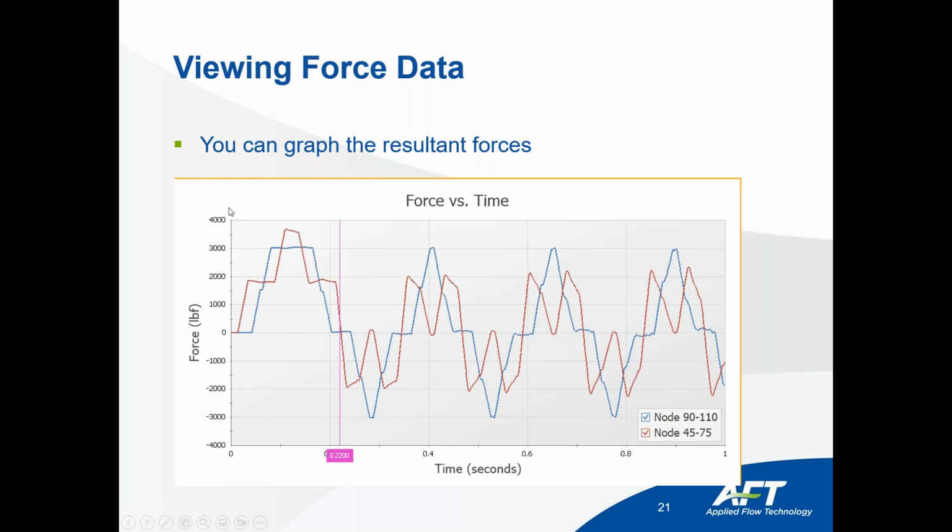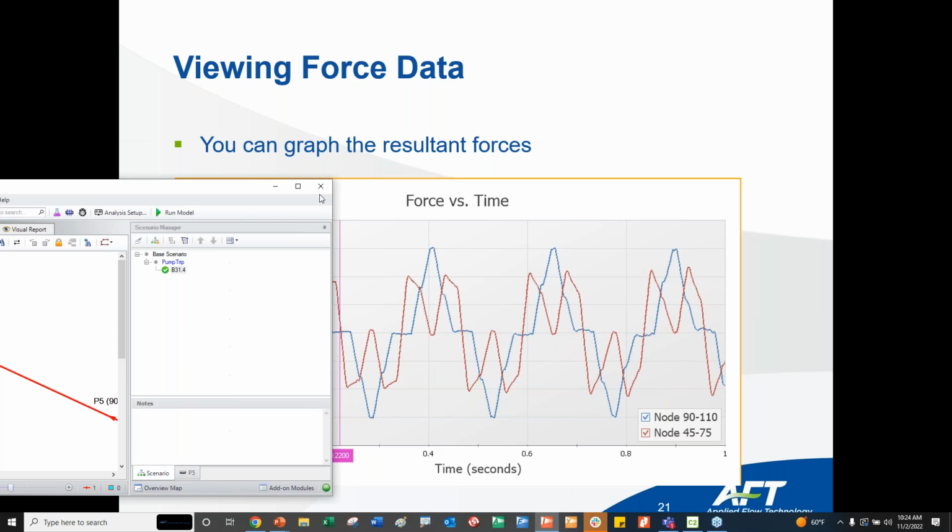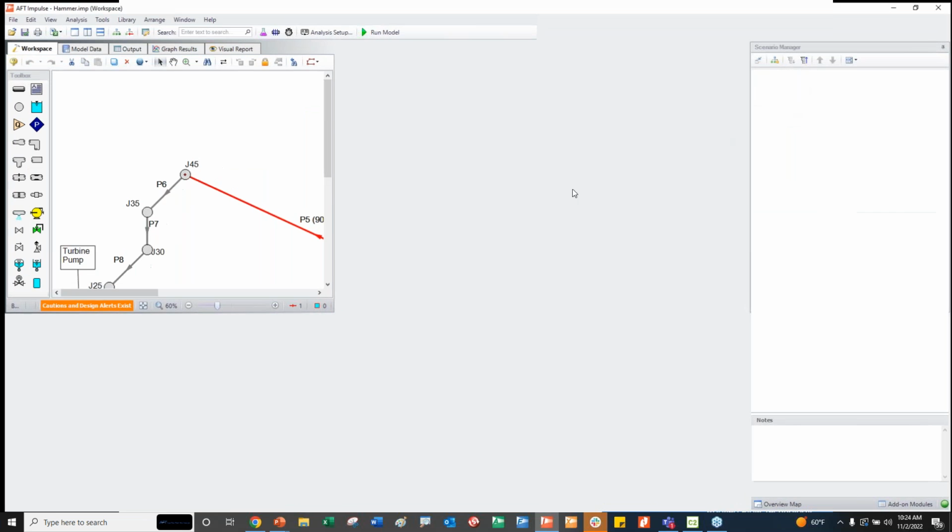After that, you can graph your force results before you export to examine how the forces are being generated, to see if they make sense. And then we'll see how to export it to a pipe stress program. So let's move on.